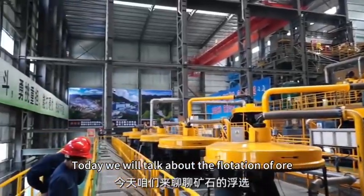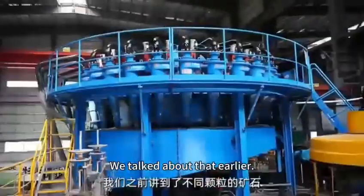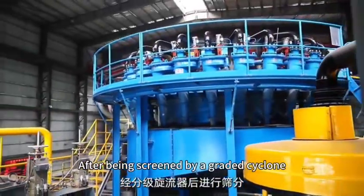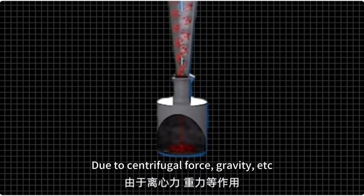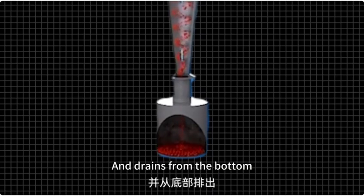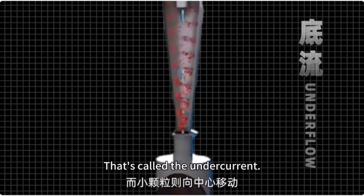Hello, today we will talk about the flotation of ore. We talked about that earlier. Ore of different particles, after being screened by a graded cyclone, what about large particles? Due to centrifugal force and gravity, they will move down the inner wall of the cyclone and drain from the bottom. That's called the underflow.